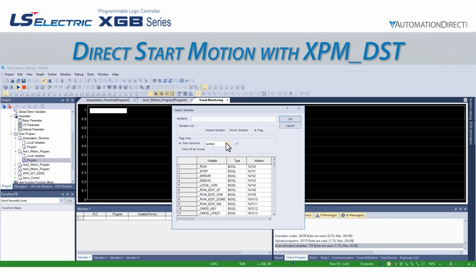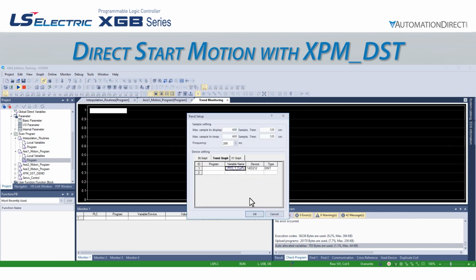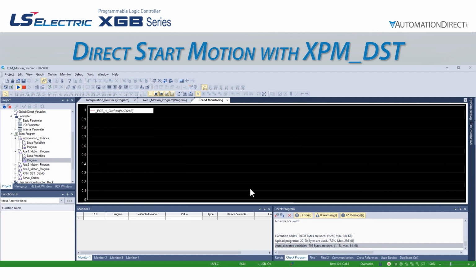This is a system flag variable that displays the current position of axis 1. We will leave the sample setting values at the defaults and click OK. If we were still in monitoring mode, the trend would begin to fill with empty data, so it is important we left monitor mode prior to adding the variable to the trend.